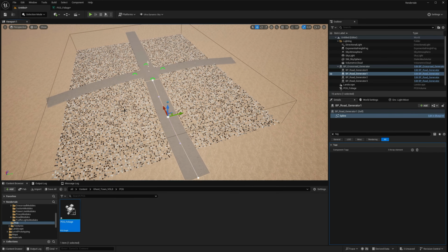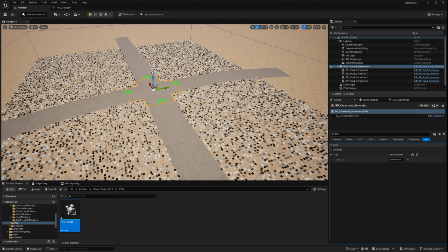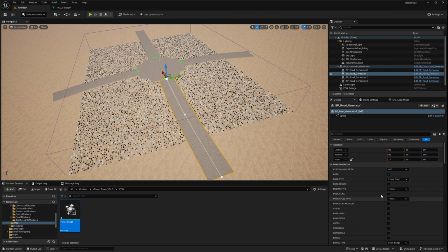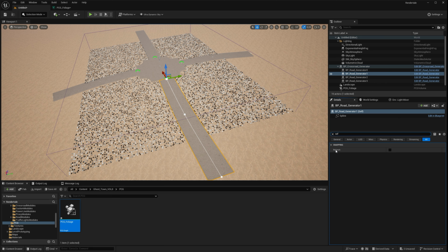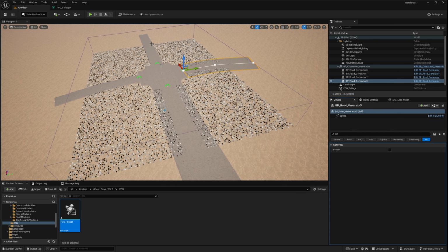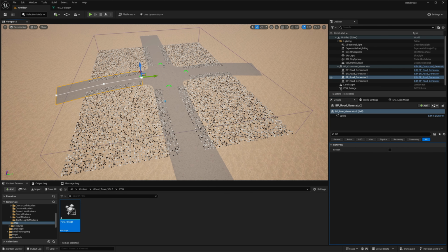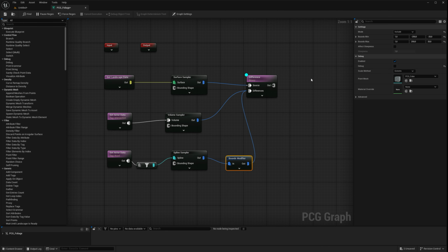If you update the layout, say you swap a 2-lane crossroad for a 4-lane one and hit refresh on the attached roads, the exclusion zones will automatically update to reflect the new geometry. If you still see points overlapping the wider roads, just tweak the bounds in the bound modifier to better match the new dimensions.